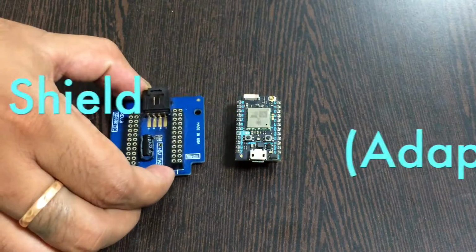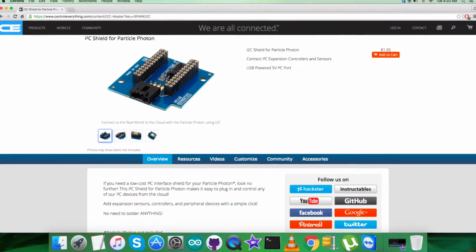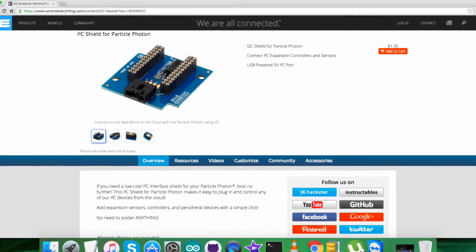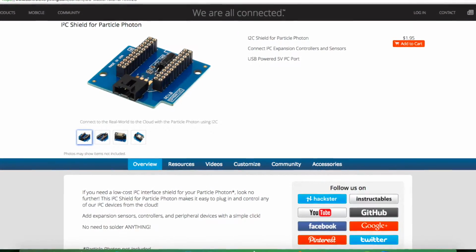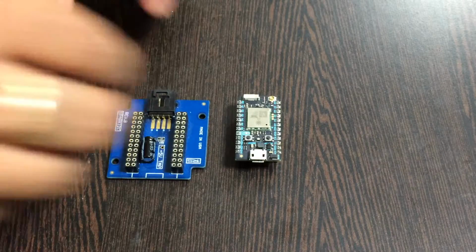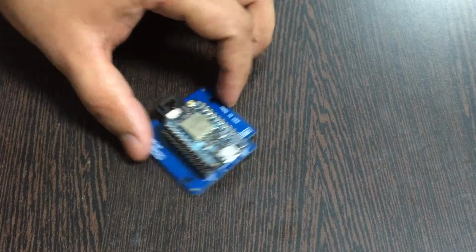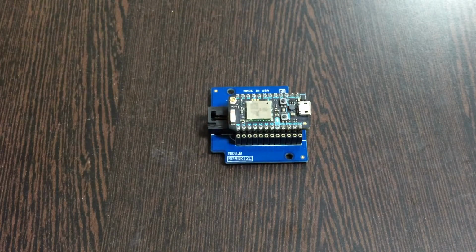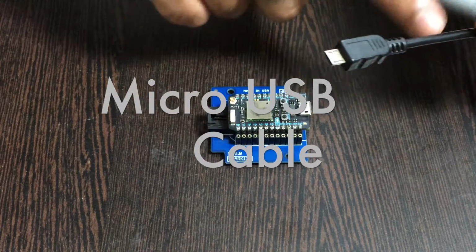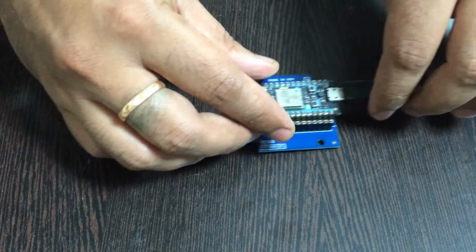Now this here is an I2C Shield. It's available and can be purchased from the website controleverything.com, and the reason we are using this shield is to make connections easier with other I2C devices. So for that, we gently place this Particle Photon over the I2C Shield and make a connection just like that. Now to power up this Particle Photon, what we require is a micro USB cable, which you can see on my screen, and gently insert it into this power jack.